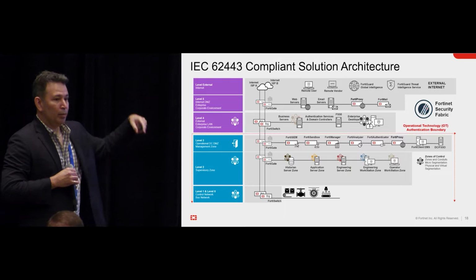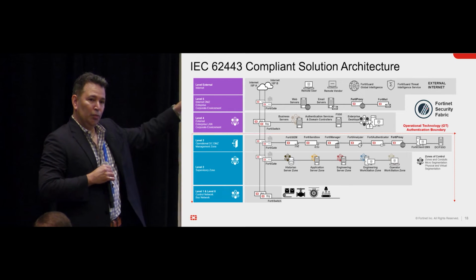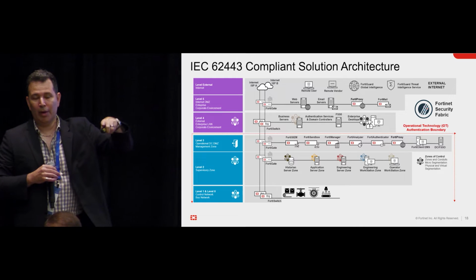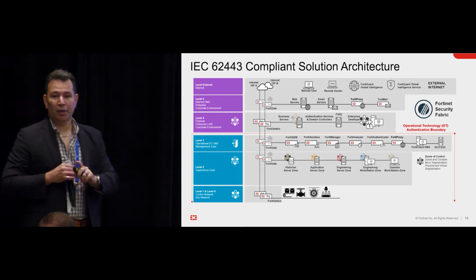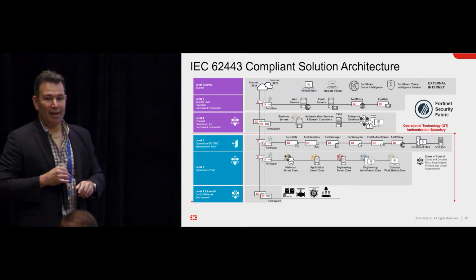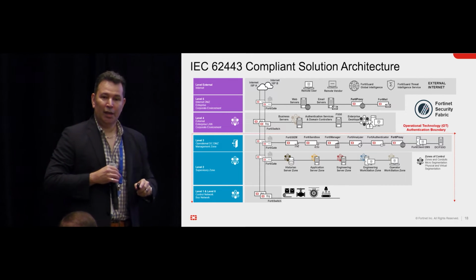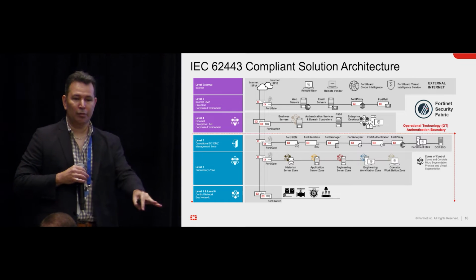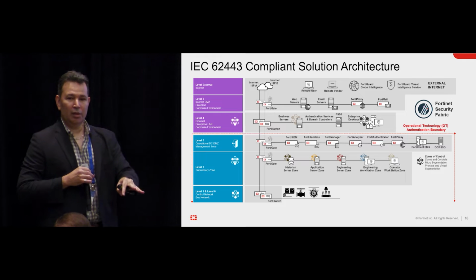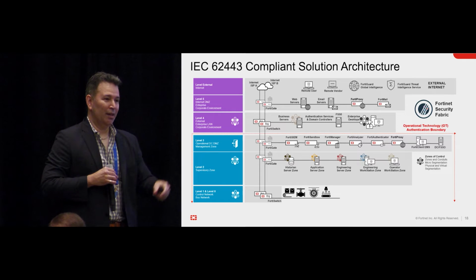But if we go back a couple of slides and look at that Modbus breakdown, now we're looking at layer 7 of the OSI model, which will allow you to do microsegmentation based on application. And that's a really powerful tool. Because for all of us that have an engineering mind, that means that I can create segmentation based on whatever comes or define it by software, or as they call it, software defined, right?